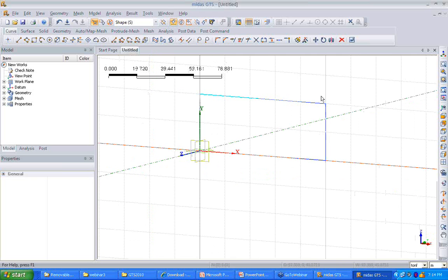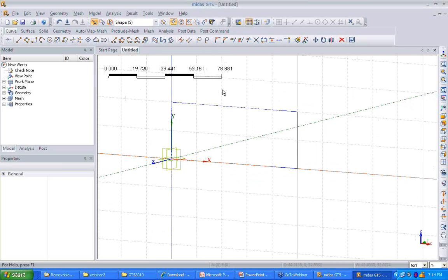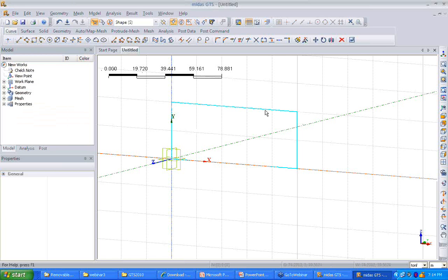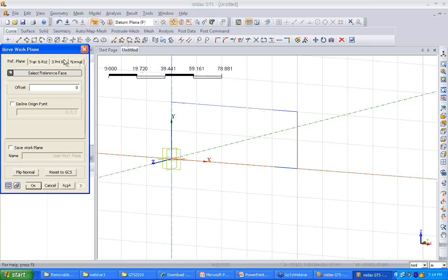We will use this wire to extrude the ground. The next part is, we will similarly make a 2D frame for the excavation layers. But before that, we see that this curve can be created on the work plane, so we need to move this work plane perpendicular to the height of the excavation layers. In short, we'll use a 3-point plane to move the work plane.